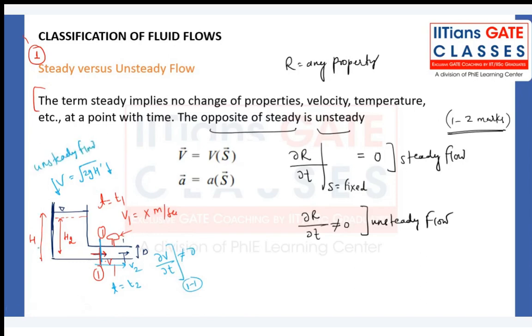because h is varying. But once h is fixed for all the time, at a particular section my velocity will be fixed unless I am changing my diameter like this, at 2-2. So again, if height is fixed at all times, from one point my velocity will be v1 only. That is my constant velocity. Of course here velocity will be increased, but that is because my location has been changed. That is a non-uniform flow, but it is a steady flow if this is fixed.